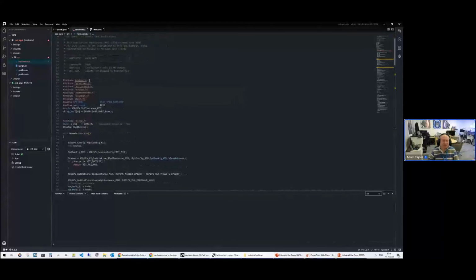And there's a few things that we've done here. So we're using the Xilinx PS SPI. We're using the system monitor drivers. We're using the math.h, which means we need to make sure we map that in with our linker. We've set the base address for the SPI MIO. We've set a maximum count, and we've defined the SPI instance here as well for the DAC.